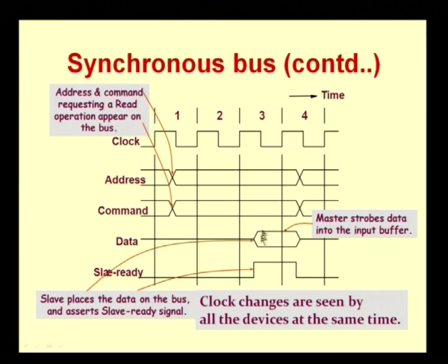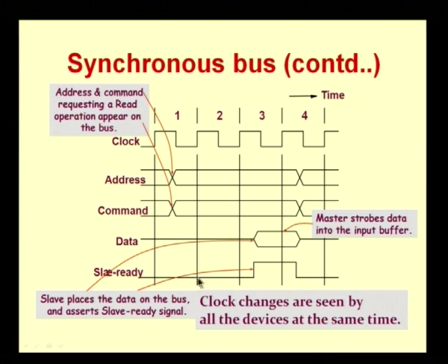So, you can see that you can have multiple clock cycles. A slower device may take more clock cycles, a faster device may finish in one clock cycle. By going in for these additional control signals, you can accommodate both faster and slower devices and not compromise on the timing. And the second thing is that if a device is not ready, it would not have put up this slave ready signal. So, you will also know that it has not responded. Both these problems can be solved with the help of this kind of additional signal that we use.